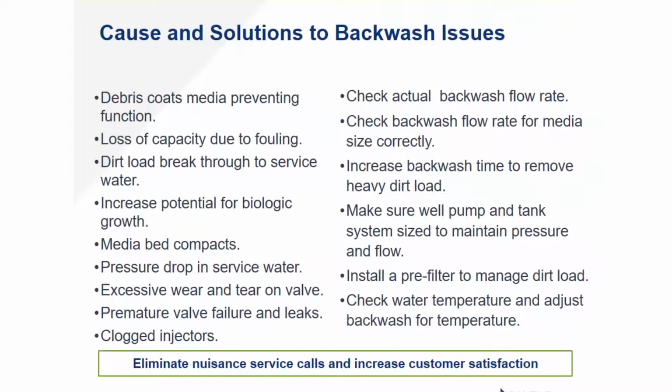So this will help eliminate nuisance service calls and increase customer satisfaction. Plus, backwashing issues are not easy to diagnose. Most of the time, this will show up as "I've lost complete flow." You pop the head off the tank and you've got sludge in the top of the tank where it's just built up over time. We've got dirt coming through the unit at the taps.